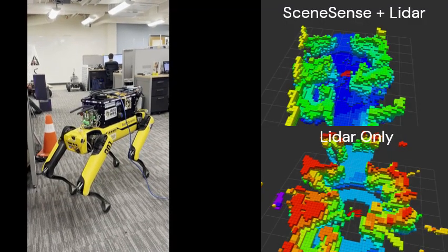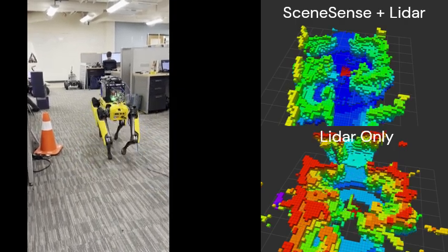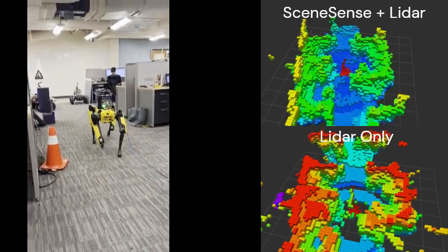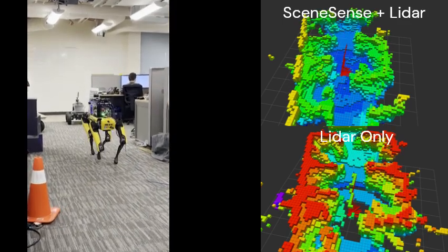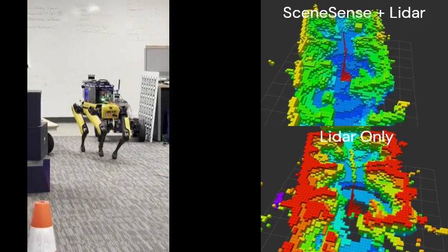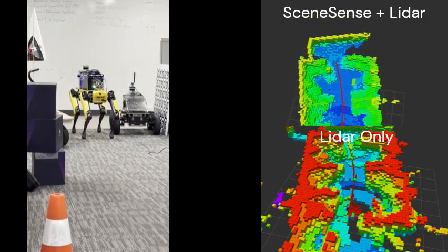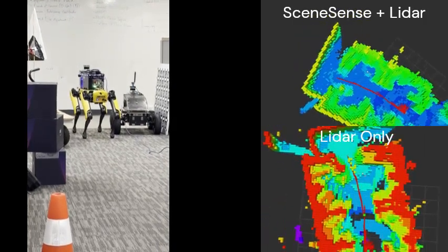Here, we show our robot-centric occupancy predictions in real time onboard our Spot robot in a new test environment. In this configuration, SceneSense is generating occupancy predictions around the robot at 2 Hz. Then, the predictions are merged into the running occupancy map using our probabilistic update rule. As you can see, the predictions enhance the running occupancy map, filling holes in occluded geometry in the scene.